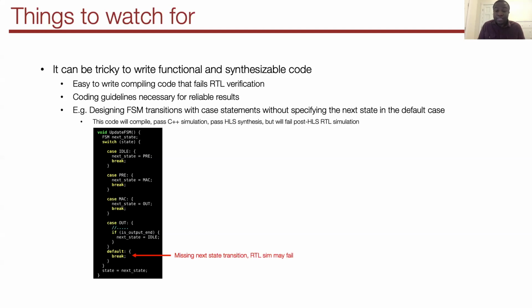So I get the sense that there is a lack of standardized coding guidelines to guarantee end-to-end functional correctness, all the way from C++ to final RTL verification. Therefore, I think designers should be wary of this and really spend time to sanitize the C++ code prior to HLS.